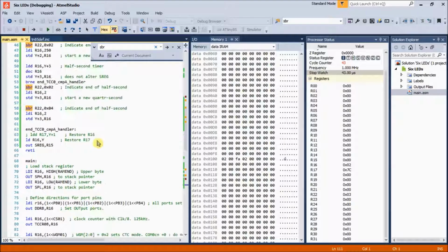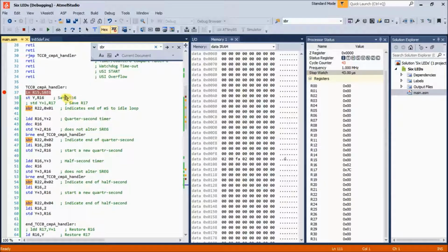If you are writing an application that requires your interrupt routine to be very fast, then this system of storing everything in memory may not be good for you. If you have enough registers to do it, you can simply keep all your variables in registers, and you can decrement a register much faster than you can recover a value from memory, decrement it, and then restore it to memory.